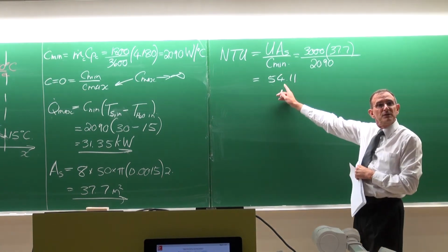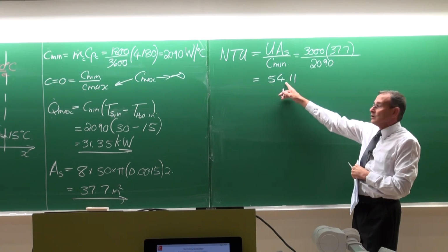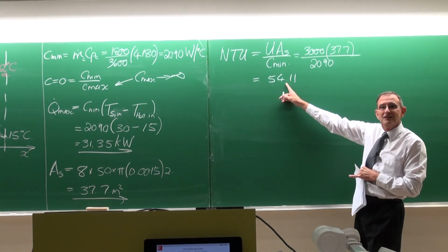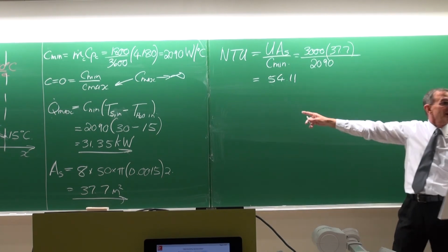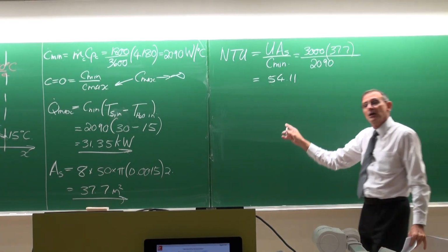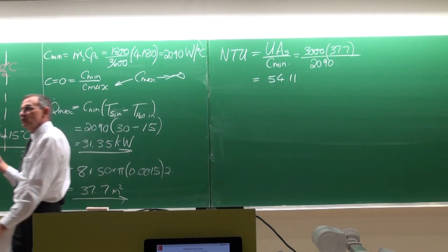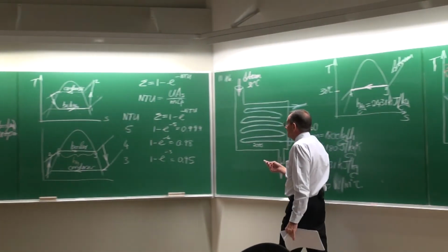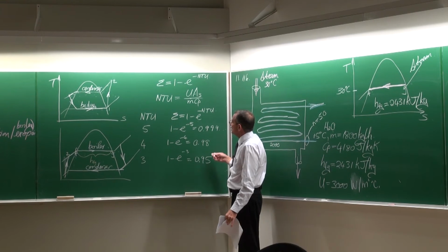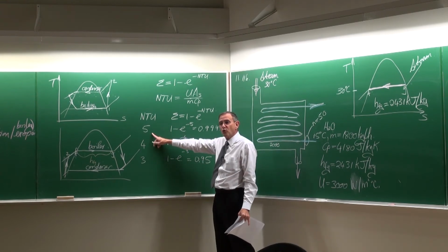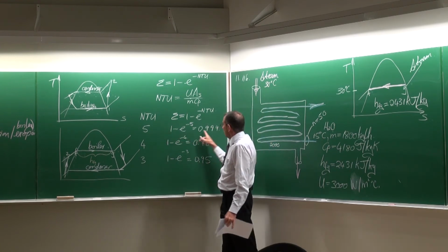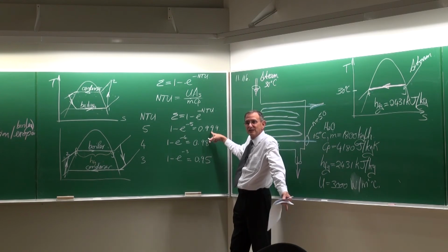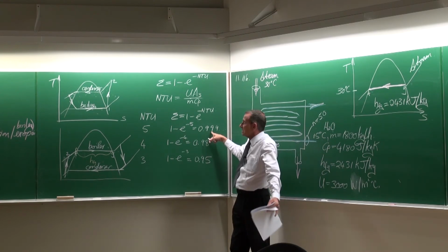Now, if you've done some heat exchanger design, you should frown here. For 2 reasons. Firstly, maybe you've made a calculation error, so you need to go and check this. But coming back to what I've already warned you on in the chapter on internal forced convection, if your NTU is more than 5, you're wasting money, because your effectiveness will already be 100% for all practical purposes.